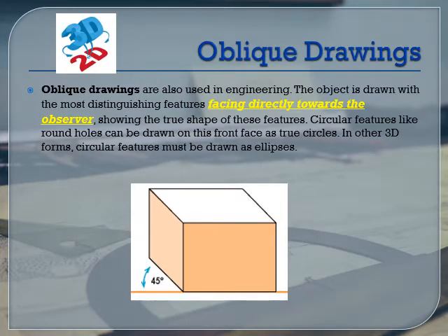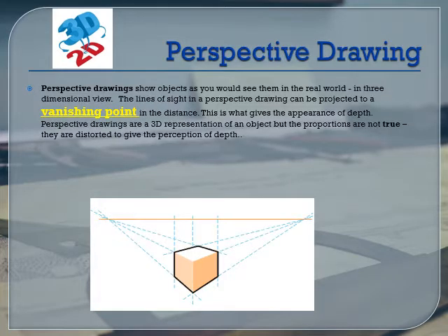Next, we had an oblique. So in an oblique, one of the faces is directly towards you, and then the other lines usually go back at 45 degrees. And there were 2 types of those, remember, cabinet and cavalier. Cavalier was the full length one drawn, and cabinet was when it was only drawn to half its length, and it made it more realistic looking.